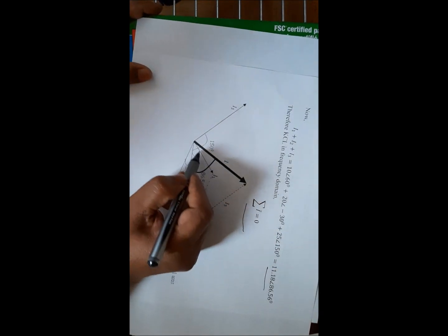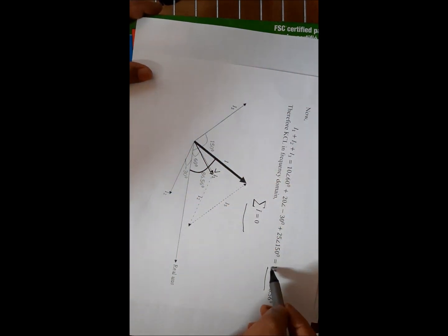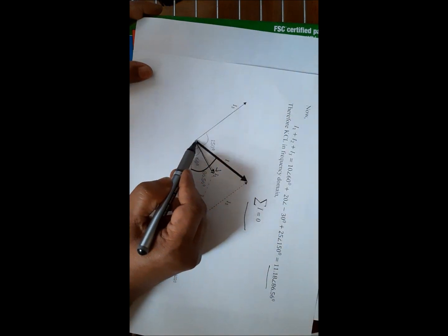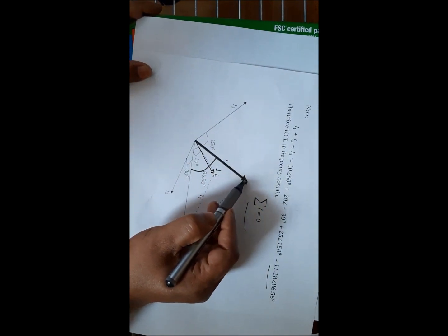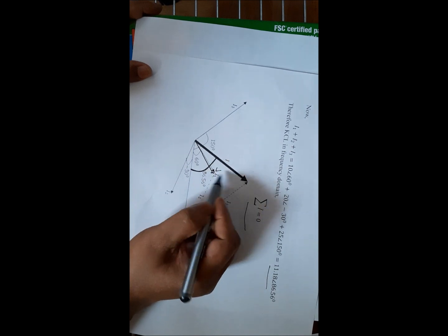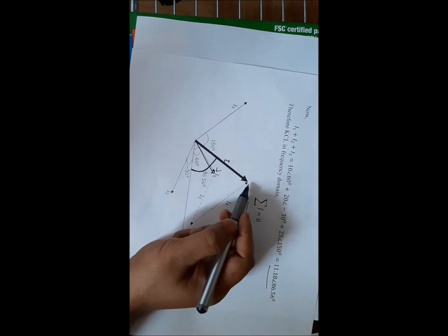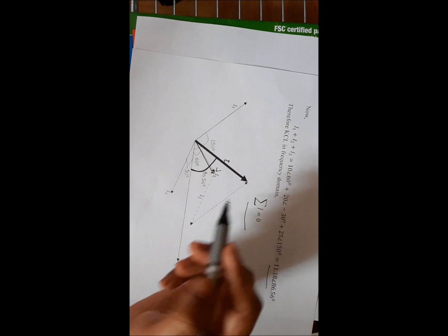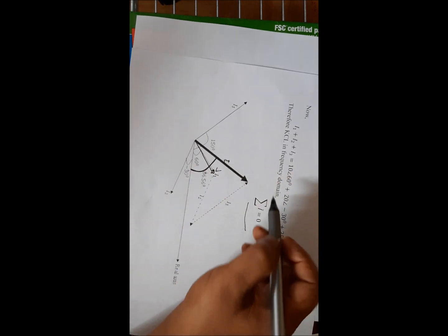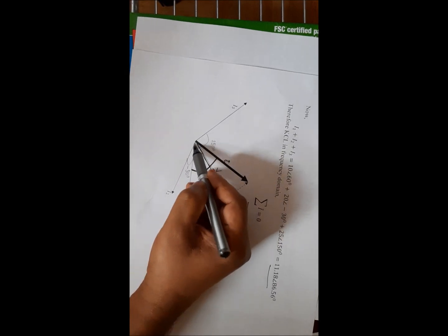So this is your voltage, 50 angle 60 degrees, and the current is 11.18 angle 86. So this is the relation between voltage and current, and you see current is leading. Current has a higher angle, so current is leading the voltage. And if you want to show the total current, I1 is the current for the resistor, I2 is the current for